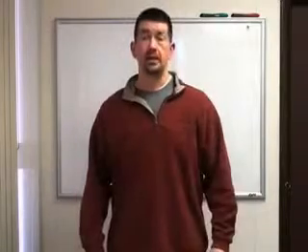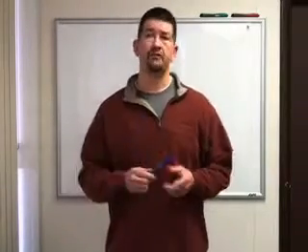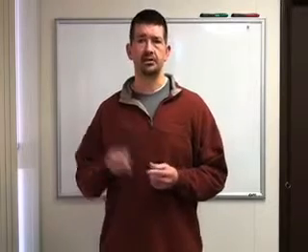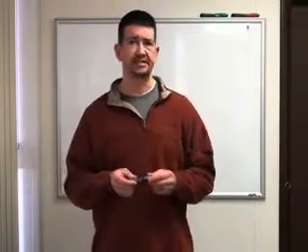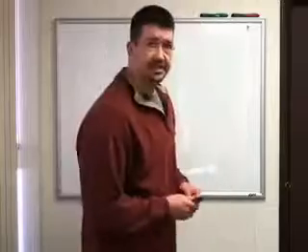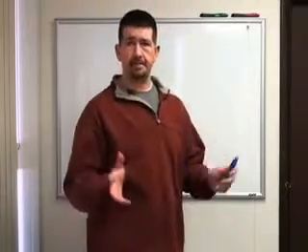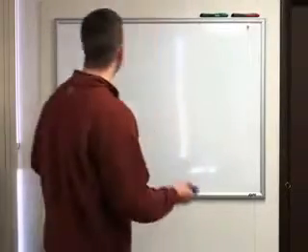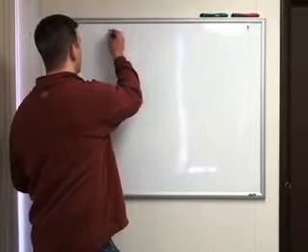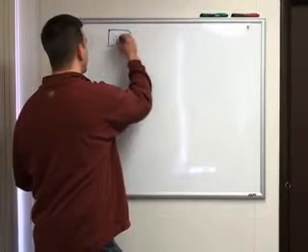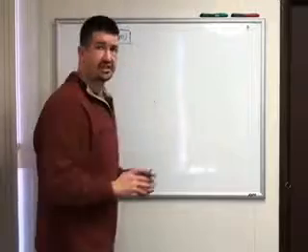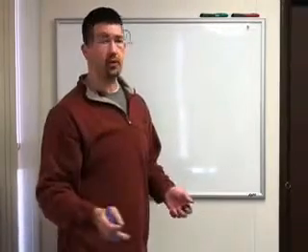Now I'm going to show you a basic home run RF distribution system, and the little system we're going to design here we'll say has 16 TVs. On a 16 TV basic home run distribution system, we'll use our example source as a cable company. And to run to our 16 TVs, we're going to use a 2-way and 2 8-ways.